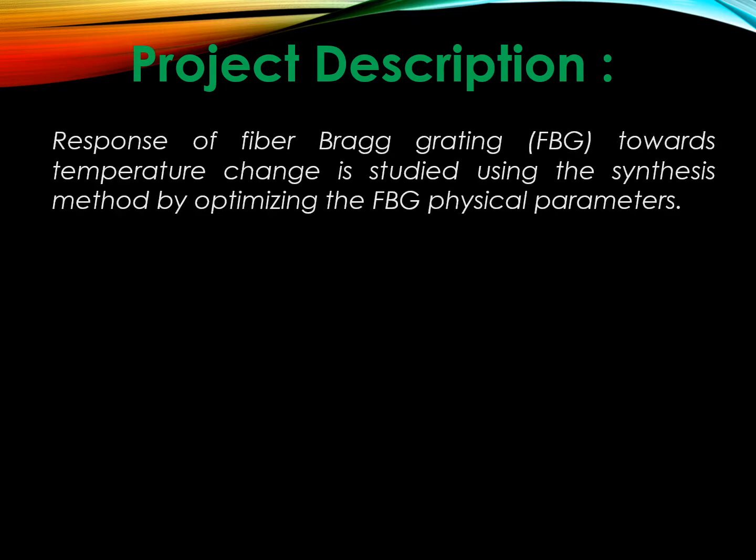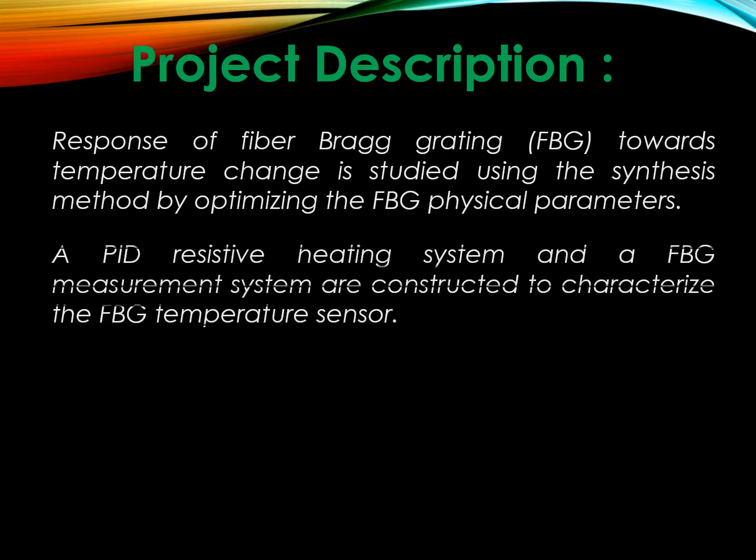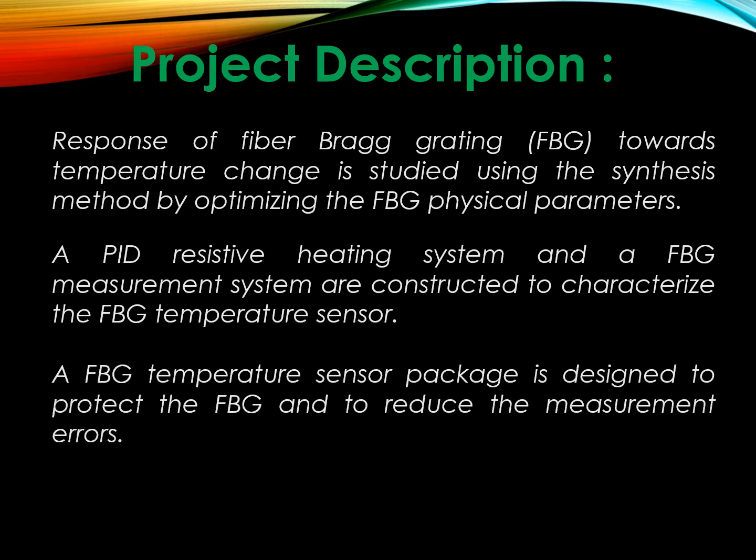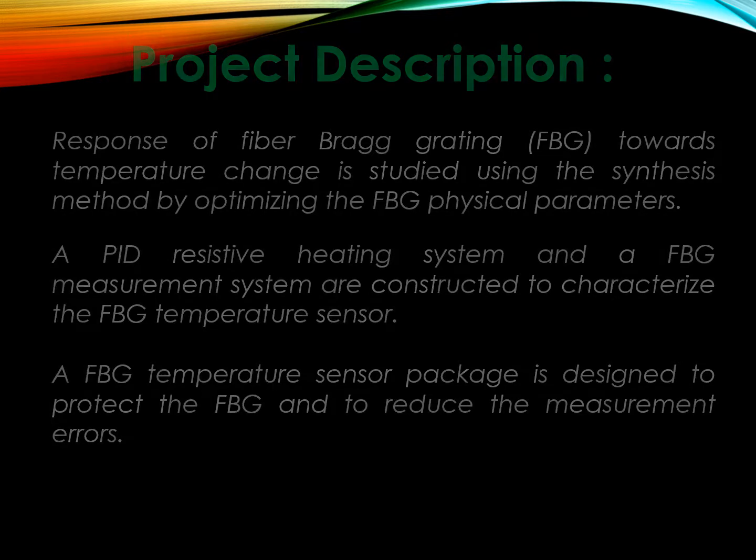The project consists of three parts. The response of fiber Bragg grating towards temperature change is studied using the synthesis method by optimizing the FBG physical parameters. A PID resistive heating system and an FBG measurement system are constructed to characterize the FBG temperature sensor. An FBG temperature sensor package is designed to protect the FBG and to reduce the measurement errors.